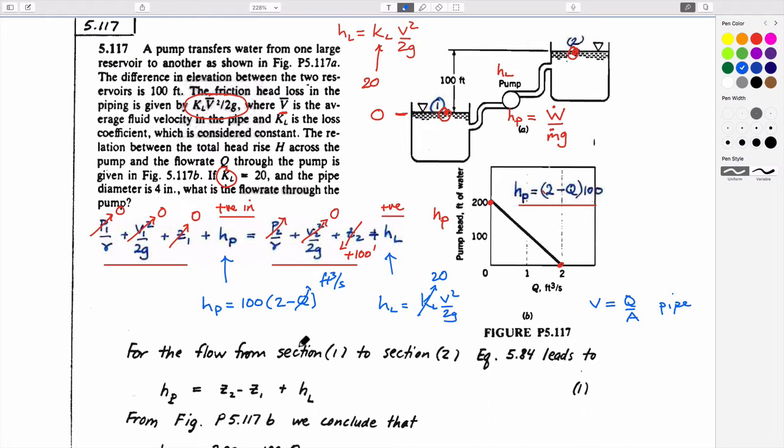So in other words, we have an expression now which identifies something in terms of Q in this term. The term for these is just Z1 minus Z2, which is in length of feet. And we have this also defined in terms of volumetric flow rate. So V squared is equal to this. This has to be pi d squared upon 4. Do we have the diameter of the pipe?